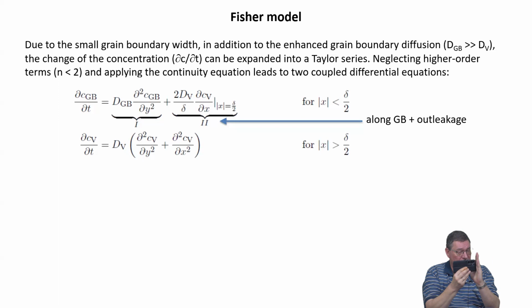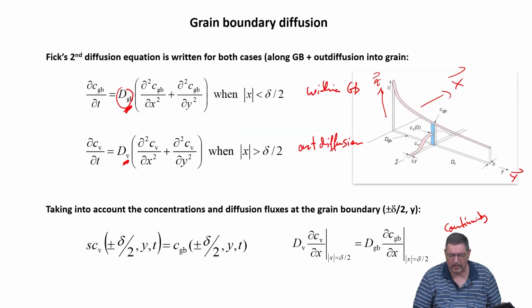So you have a given plane, and then diffusion is going along this plane. If you would have differences, then this is not described by this pure boundary, but then you would have some obstacles locally in the boundary. But for this Fisher model, which describes the boundary as a homogeneous slab of material with thickness delta, in this Z position or in this Z position, you would have the same concentration profile as a function of distance to the original plane. Yeah?